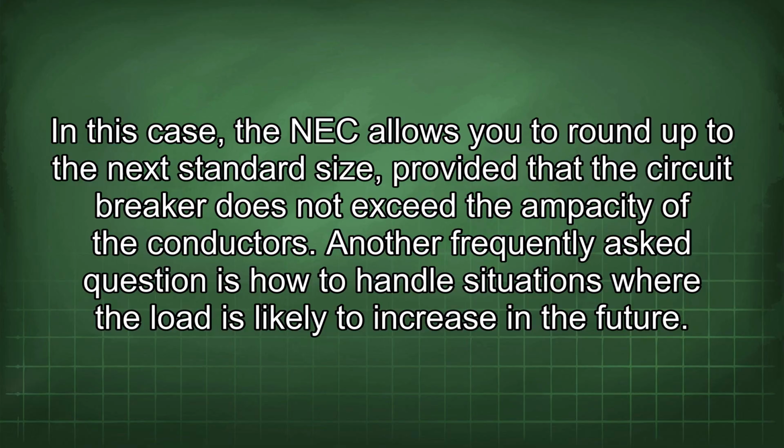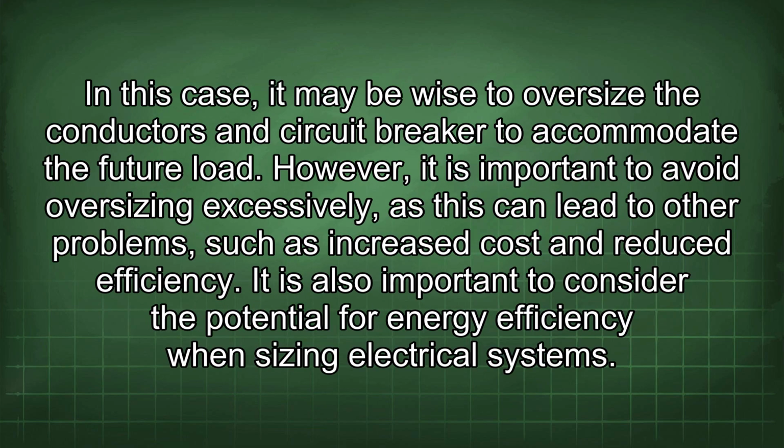Another frequently asked question is how to handle situations where the load is likely to increase in the future. In this case, it may be wise to oversize the conductors and circuit breaker to accommodate the future load. However, it is important to avoid oversizing excessively, as this can lead to other problems such as increased cost and reduced efficiency.